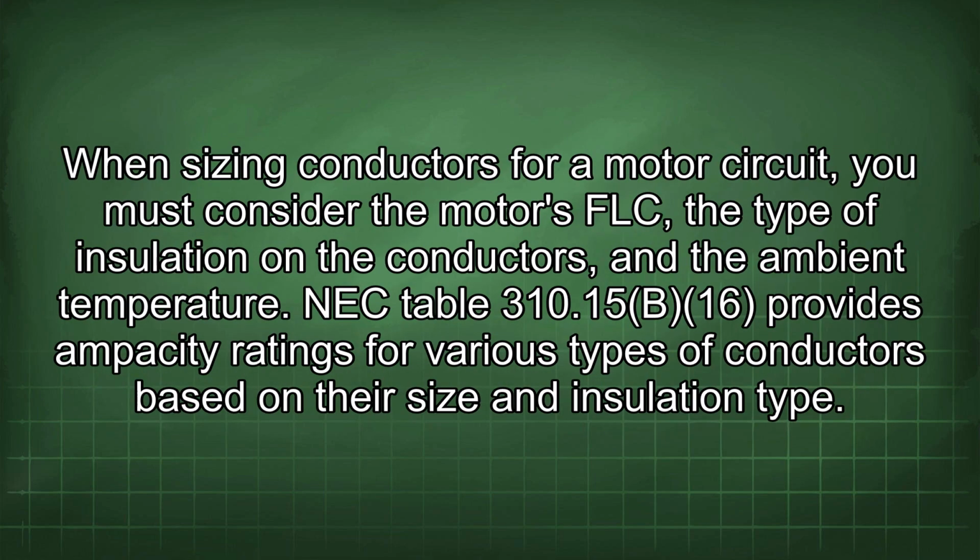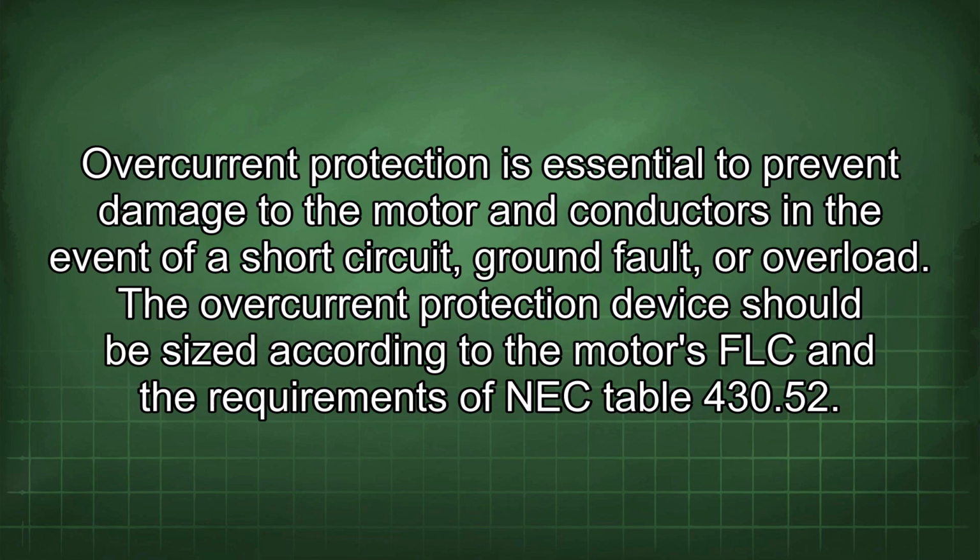When sizing conductors for a motor circuit, you must consider the motor's FLC, the type of insulation on the conductors, and the ambient temperature. NEC Table 310.15(B)(16) provides ampacity ratings for various types of conductors based on their size and insulation type. Overcurrent protection is essential to prevent damage to the motor and conductors in the event of a short circuit, ground fault, or overload.